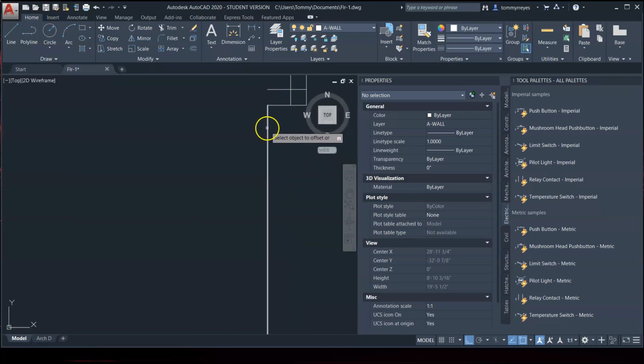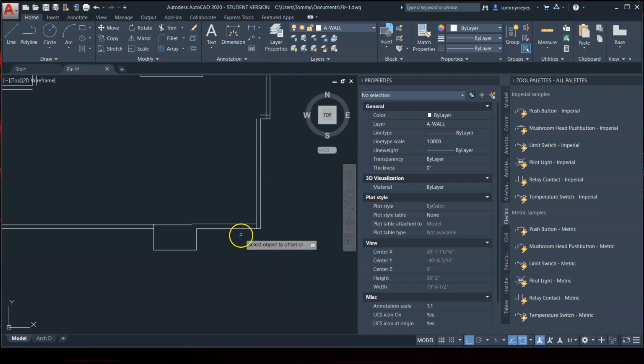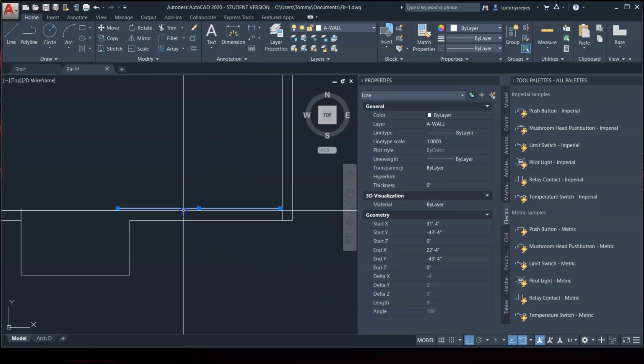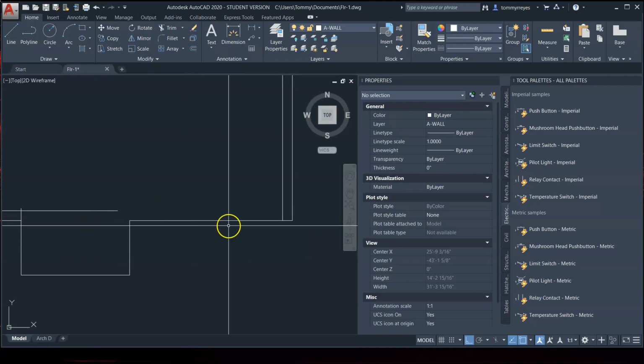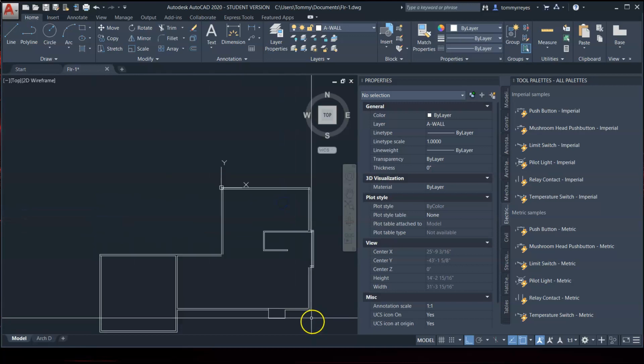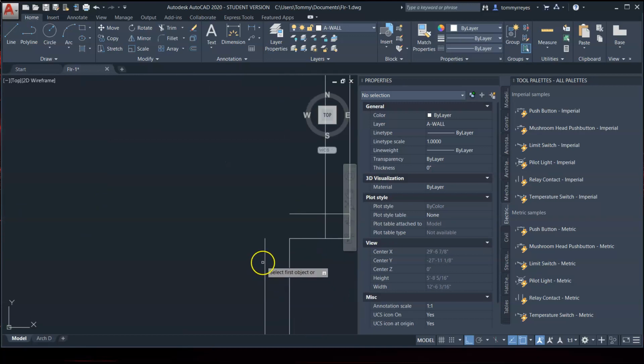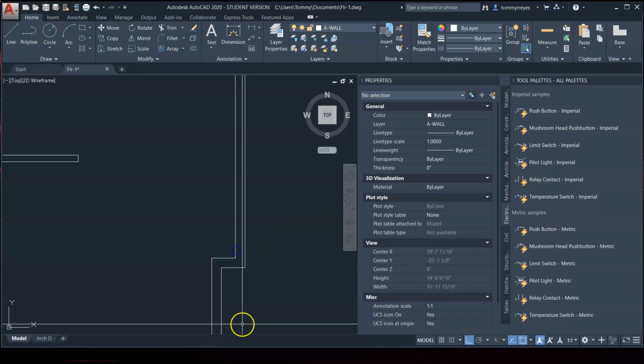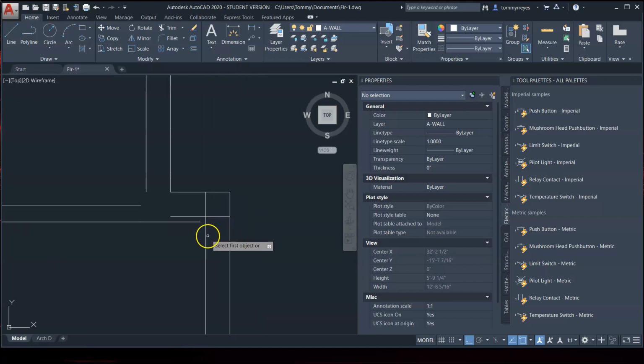So I'm going to go ahead and delete this, because I can fillet here and here at a 0. Here and here. And again, I'm just pushing spacebar because I entered the fillet command one time.